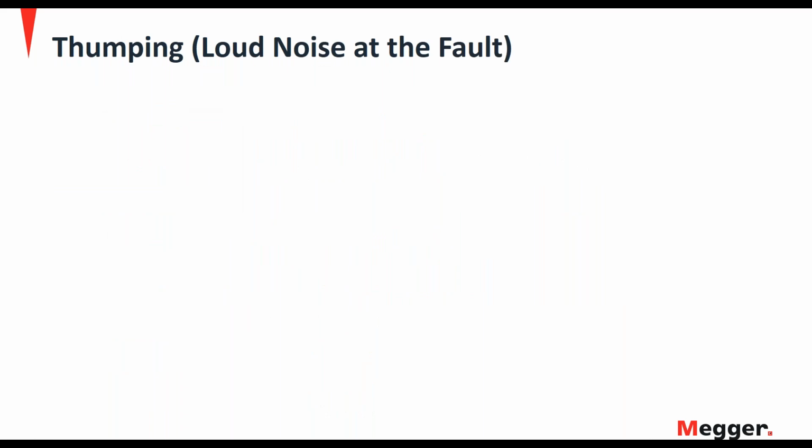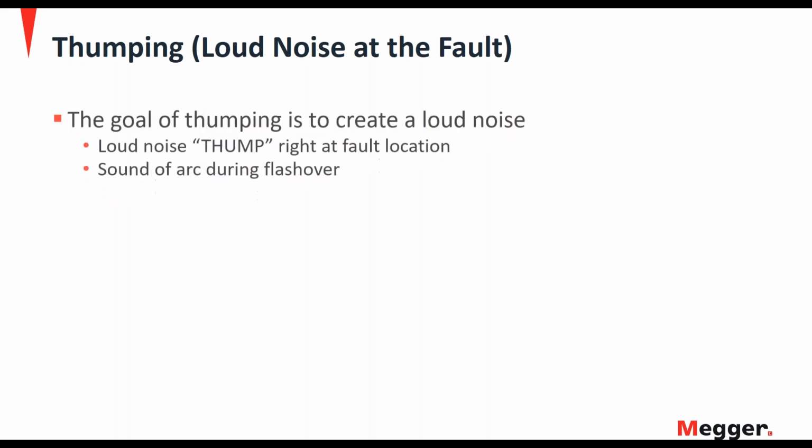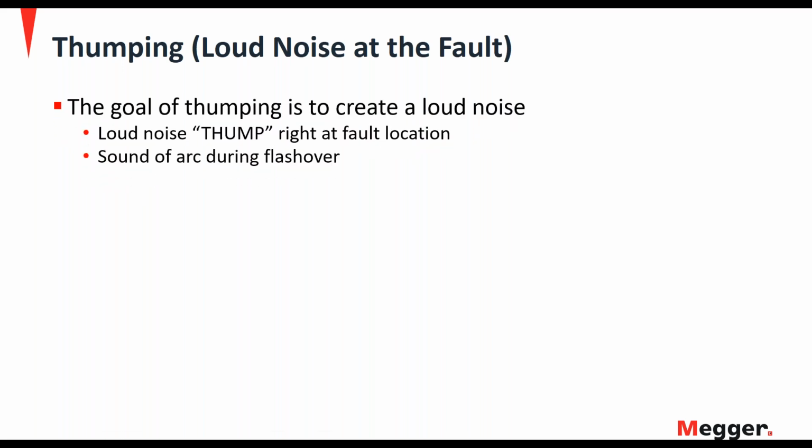So before we move on, let's talk just a little bit about thumping. Thumping, we want to make a loud noise at the fault. That's the goal, to create a loud noise. And we want to be able to, at the fault location, stand on it and hear and feel that thump. And so the louder it is, the better.